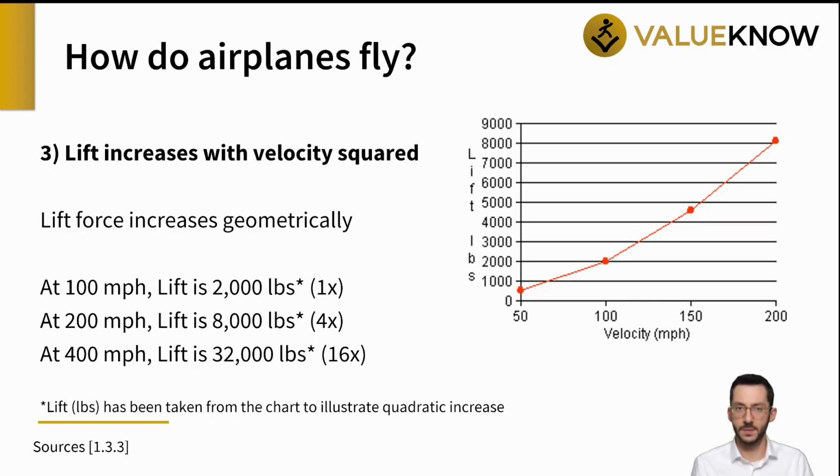The same happens with drag, and you can test it out yourself to get more of an intuition. Say that you are driving and you put your hand outside of the window. If you are driving at 30 miles per hour, you will notice the air, but it won't be making much force on your hand. If you accelerate to 60 miles per hour and you put your hand out again, you will for sure notice how the air is pulling your hand back 4 times as much as if you were at 30 miles per hour.